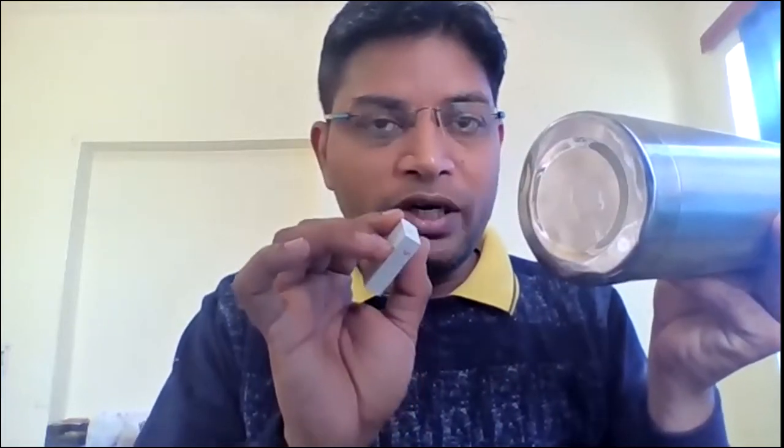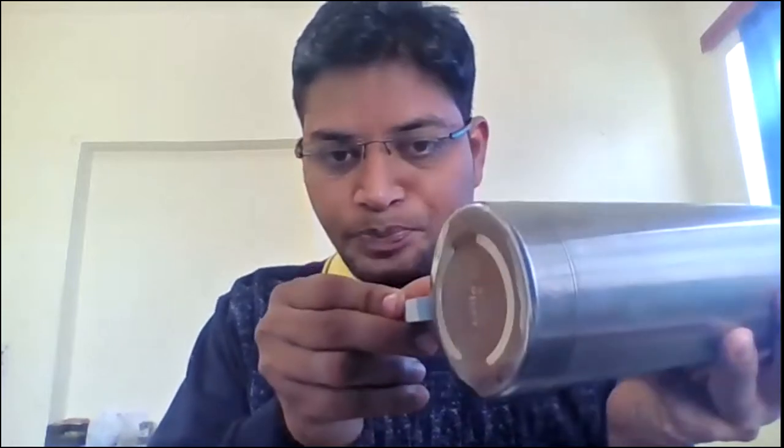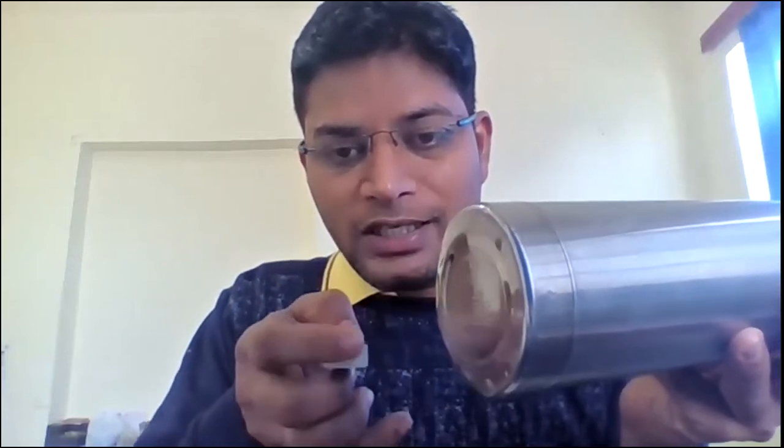There will be removal of the material, but large forces are required, because this is not the cutting edge, this is a surface, right? Similarly, this is the end face. When you give the initial depth of cut, the tool is initially here, and when you give the depth of cut, it will move in this direction. Now this complete face is coming in contact with the periphery, right?